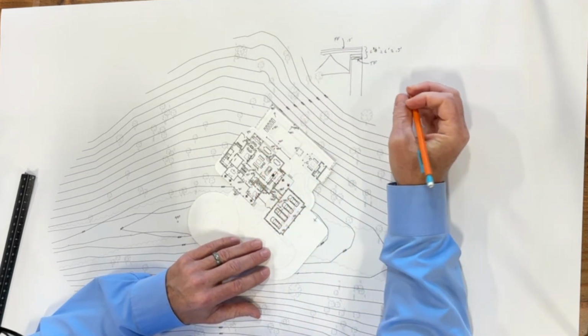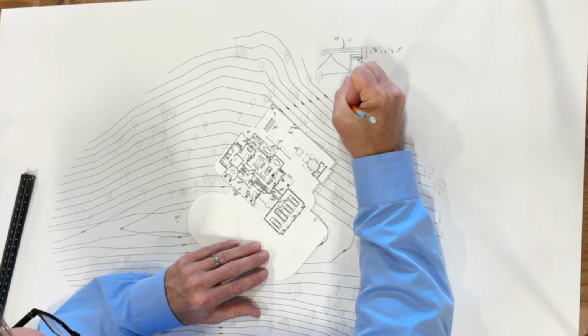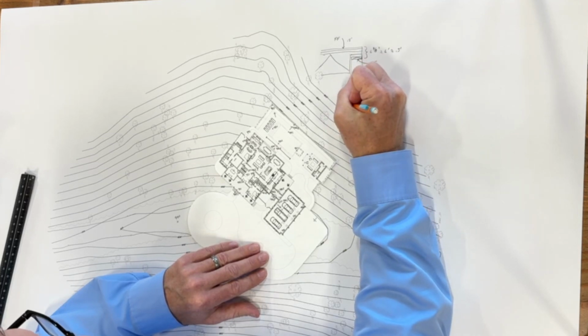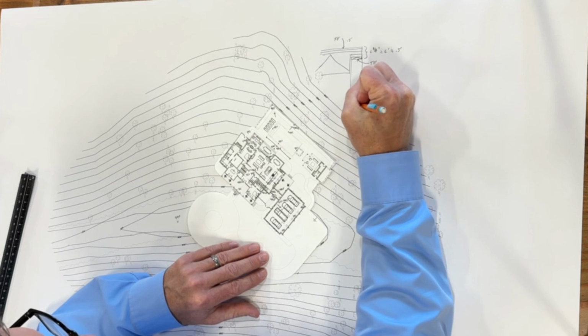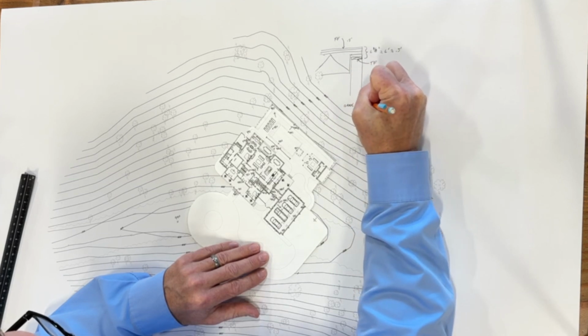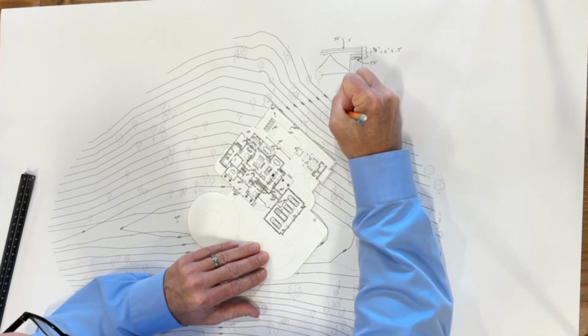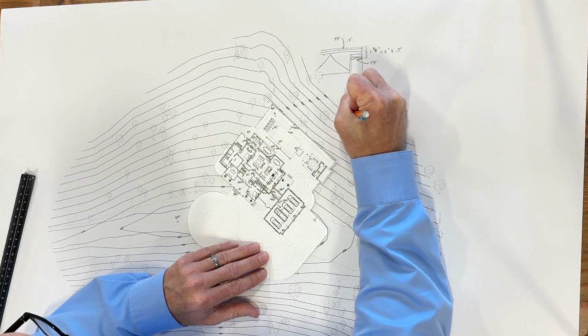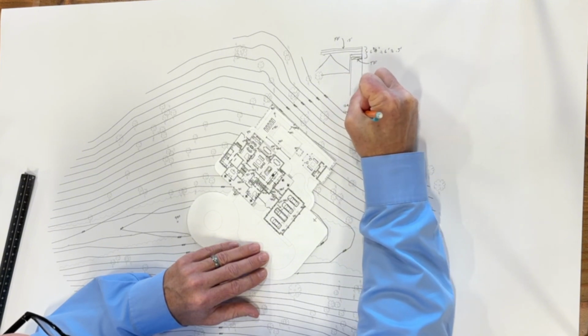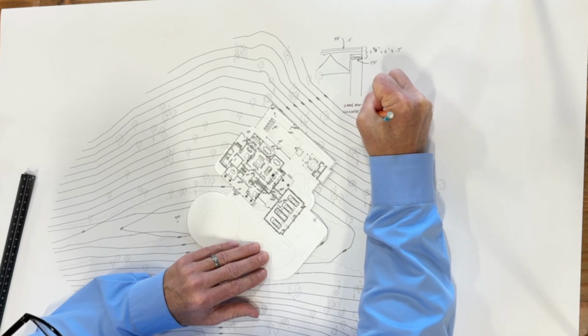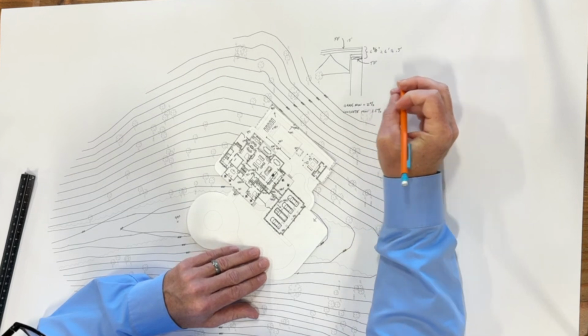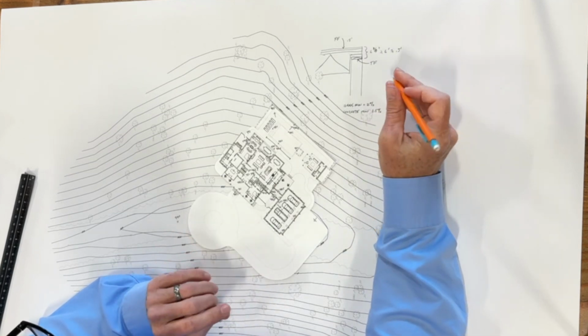And key dimensions too are whenever something is going to drain, for grass, the minimum slope to drain water is 2%. For concrete, the minimum slope is 1.5%. Some people would say 1, but I think it'll make too many bird baths where water just stays.